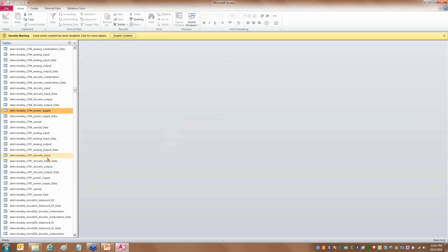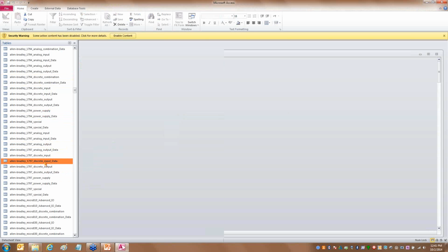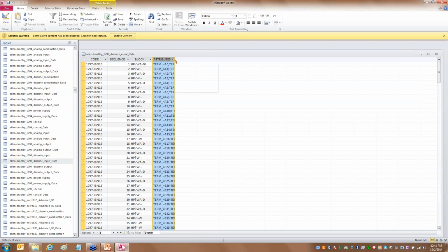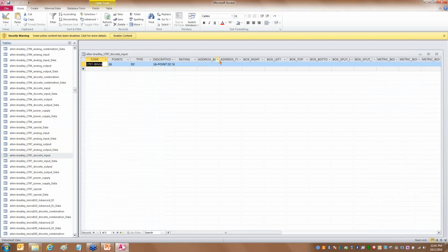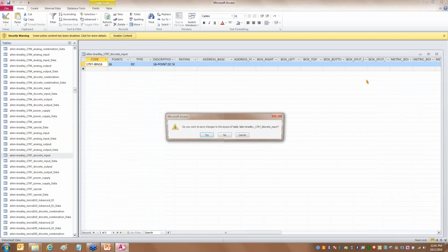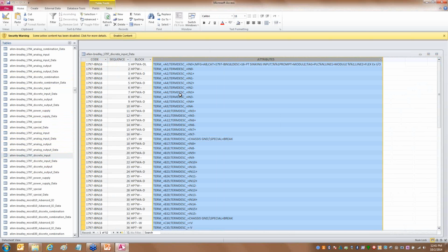We'll say no, there's only one in that one, so let's pick a different one. Let's go to the 1797 discrete. Yeah, that one's got a bunch of them. There's always two, and one of them is the address base where you can tell it decimal, octal, or hexadecimal, and then you've got the one after that that tells how it's created. And you can see in each one of these there is a tag for PLC %N in the attributes column. So it's important to know your column name to use the VBA I'm going to be using.